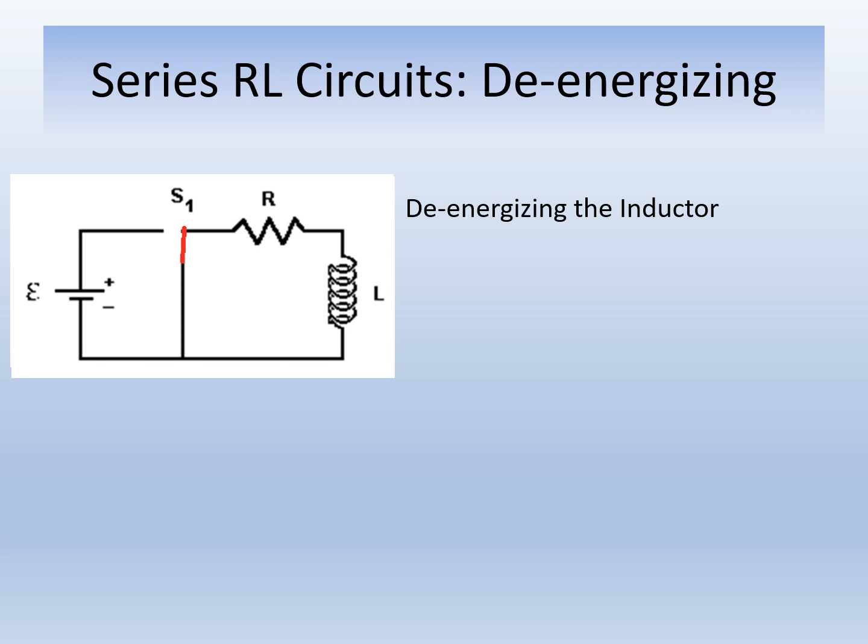And when the magnetic field dies out, the flux in the inductor is going to be zero. But this change is not something the inductor will like. So the inductor is going to oppose this change and re-establish the initial situation. So the inductor will induce voltage to re-establish the current the battery was passing.